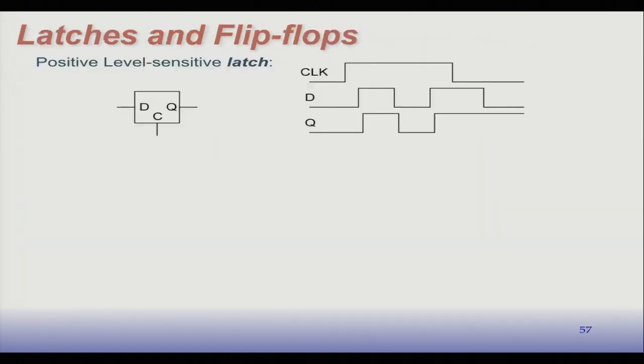Okay, so that brings me to latches and flip-flops. We haven't talked about the circuits of flip-flops. It's important to understand how we build flip-flops with transistors. Okay. And we're going to start by talking about how we build latches. First, I think I've defined this earlier, but I'm going to define what a latch is versus a flip-flop. They're not exactly the same thing. They both store values. But a flip-flop has this characteristic of the edge-triggered behavior. Right? We know a flip-flop captures its input value on the edge of the clock. A latch can capture its value according to the level of the clock.